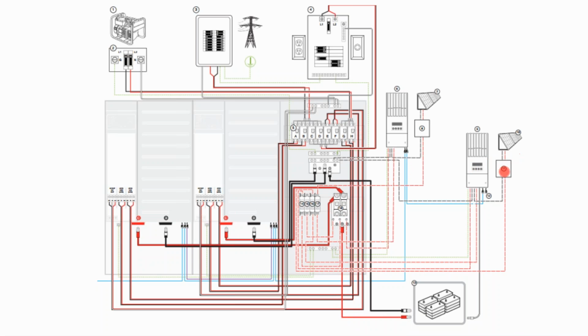but we have to remember that our solar array is going all the way up to 600 volts in a commercial setting. In a utility scale setting, they can go up to 1,000 volts or even higher. And then we have to regulate that voltage via our charge controller.